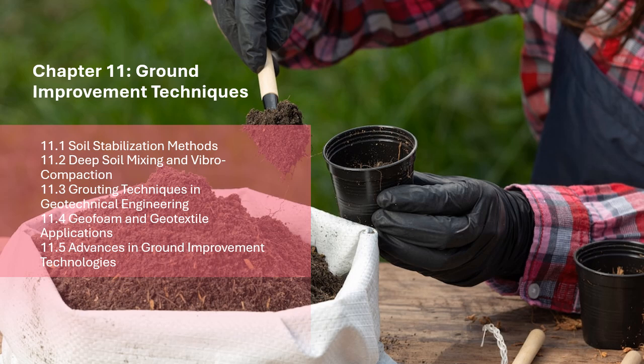11.4.2.2 Applications of geotextiles. 1. Soil reinforcement. Geotextiles are commonly used to reinforce weak or loose soils. When placed between soil layers, geotextiles improve the soil's load-bearing capacity by distributing the applied loads and reducing the potential for settlement.